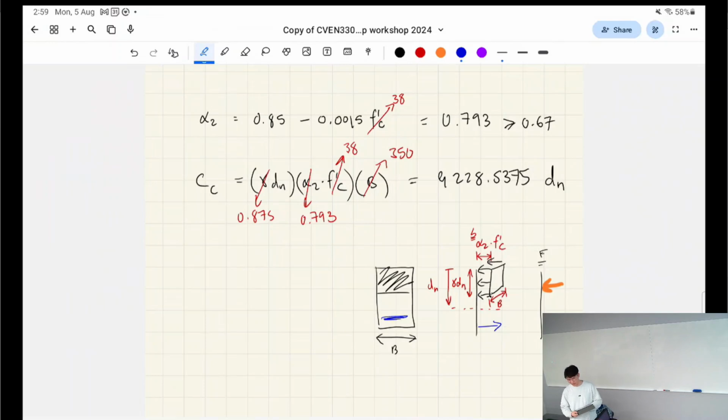Okay, maybe I should talk about what determines yielding. Remember when I was talking about strain, right? So when you pull the bars enough, or if you push the bars together enough, they reach the yield point. They reach when the bucket is full, right? That's when your stress is equal to fsy. That amount that it's stretched is dependent on how far it is from the neutral axis. So the further away it is from the neutral axis, the more likely it is to be yielded, right?